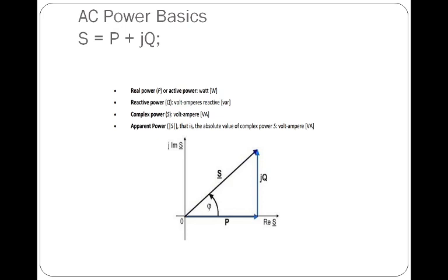We should also note that if you have two apparent powers, you cannot simply add them, just like you can add true power. If you have true power of 5 watts plus 3 watts, you simply say you have 8 watts. But if it is 5 VA plus 3 VA, you cannot add, because they have different displacement. The phasor angle between the current and the voltage might be different, so you get a different value. It's only true power you can easily add. You cannot add apparent power except when they have the same phasor angle, which gives them the same power factor.